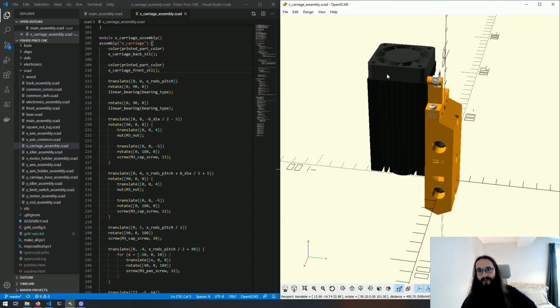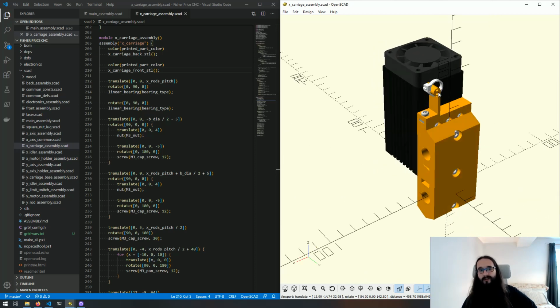This one just holds the wires coming out of a laser, and I've tried to figure out a solution to keeping them slightly more rigid than the incredibly flexible silicone insulation that they come with, because I don't want them to get cut by the laser, or mess up the workpiece.